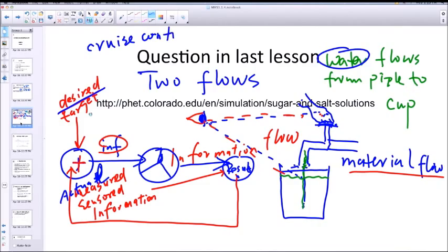Let me give you a cruise control example. Say you set your target speed as 70 miles per hour on the highway, and the cruise control system starts to increase or decrease depending on the measured speed. If it's 50 miles per hour right now and you need 70, the information means you need to speed up, so the accelerator pedal pushes further down, until, say, the next measurement is 60 miles per hour.